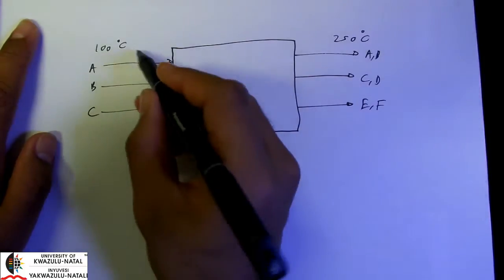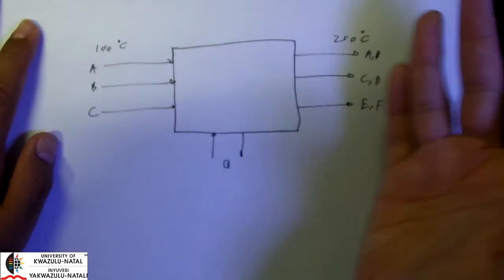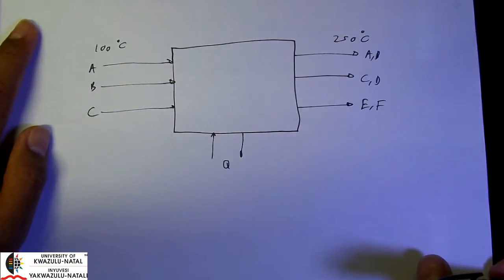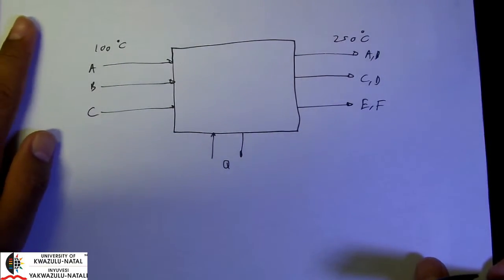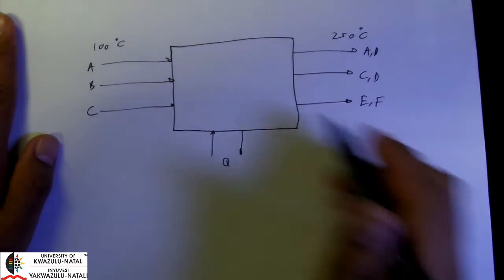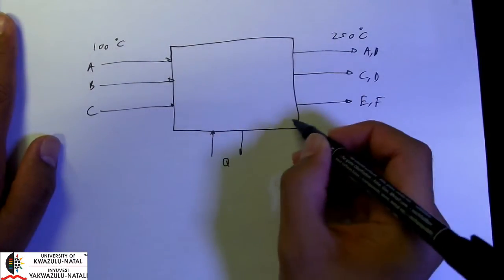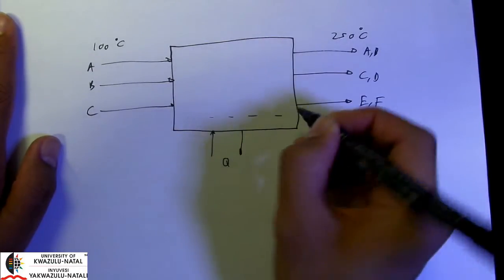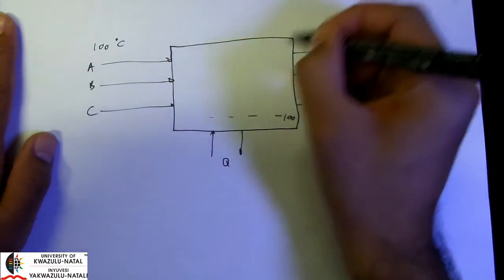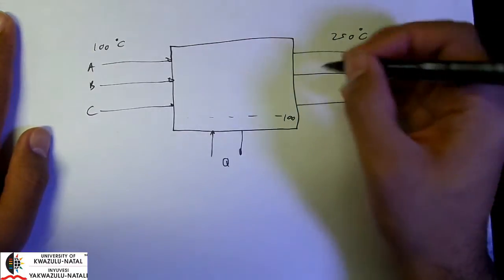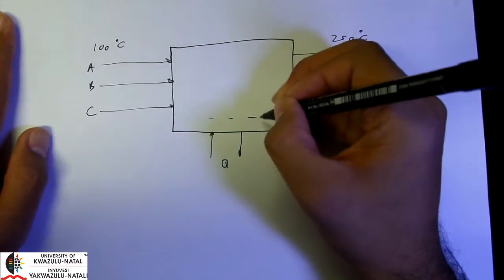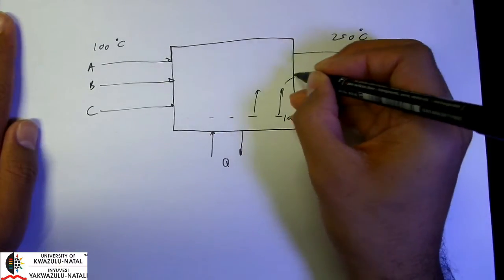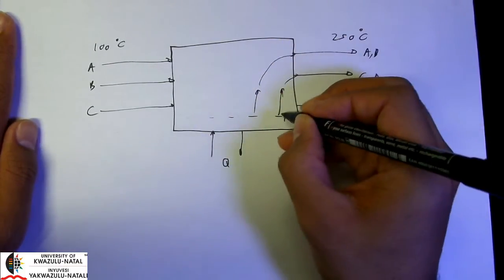It can be expressed at our reference temperature, whichever reference temperature that we need or we want to use. So if I say that my reaction is at 100 degrees, so I'm working at a 100 degree line, but now my products are at 250, so I simply have to use my sensible heat and my latent heat to get up to that 250 degrees.